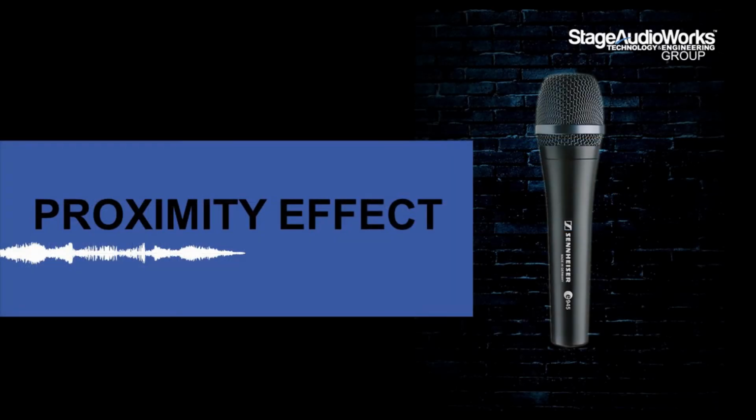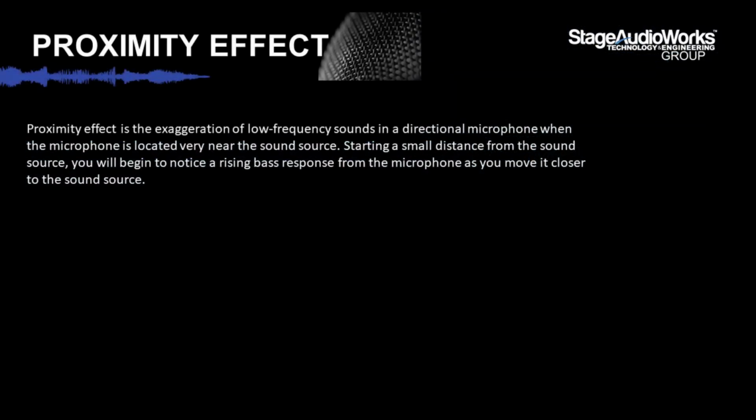The next thing we're going to discuss in mics is proximity effect, which is the exaggeration of low frequency sounds in a directional microphone when the mic is located very near the sound source. So if you start with a vocal from a small distance from the sound source and move closer to the sound source, you'll notice a rising bass response from the mic as you move it closer.